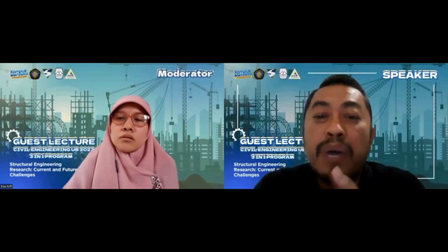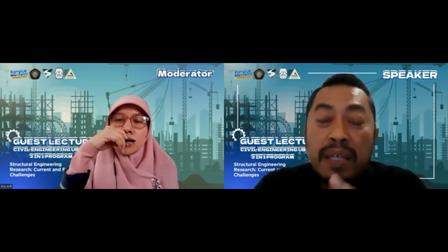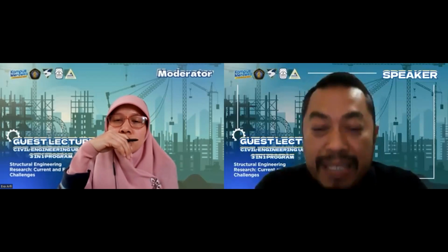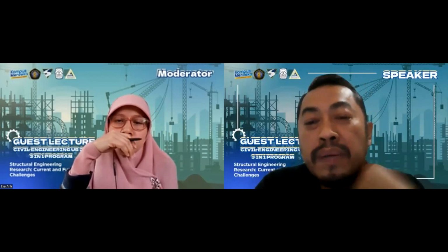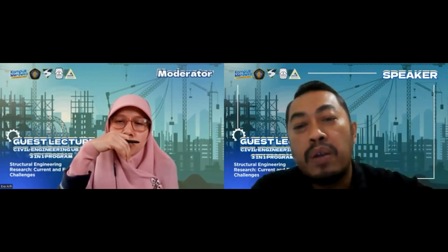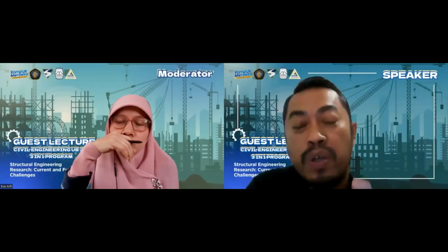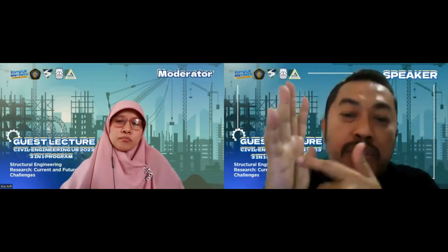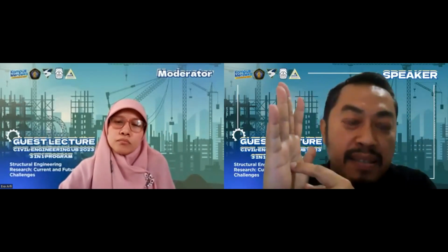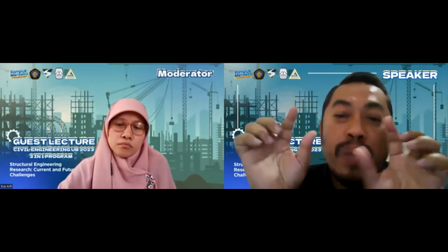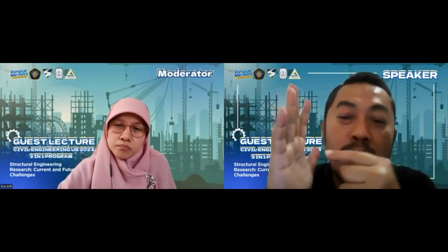Because sometimes you can't go very near, for example, when the structure being tested suddenly fails, like in shear, punching shear, or even impact. For example, I'm planning to do a bulletproof wall test, so I need to go to the army and let the soldiers shoot. For this one, I use contactless measurement to see the impact because it's milliseconds. I use DIC with a really high resolution camera to see what happens when the bullet goes through the panels.